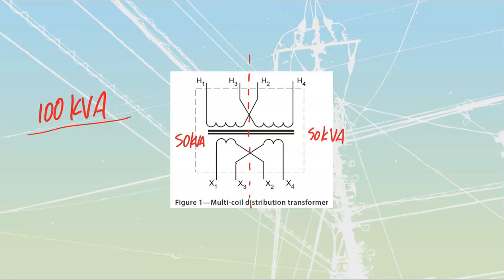The next part that they talk about is going to be the voltage part. What they give us is some slash ratings and then a hyphen. So before we even write out what it is, we need to identify what our slash ratings themselves actually are. If I've got a number that is x slash x, and then a hyphen, and then another x slash x, this hyphen over here stands as my break line for high side to low side.